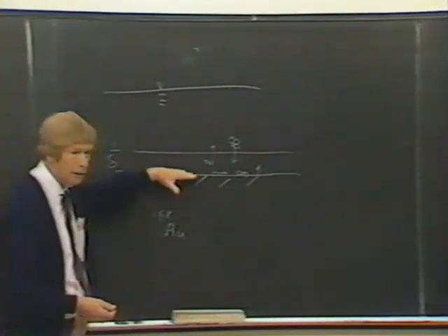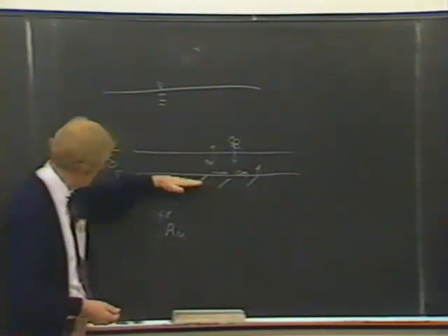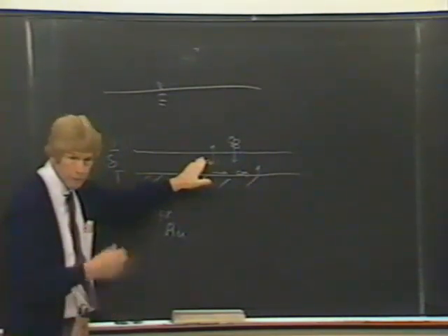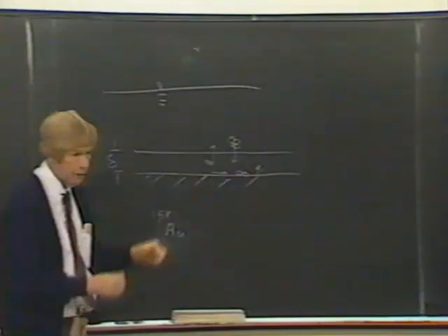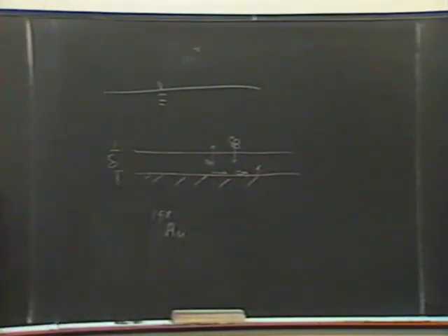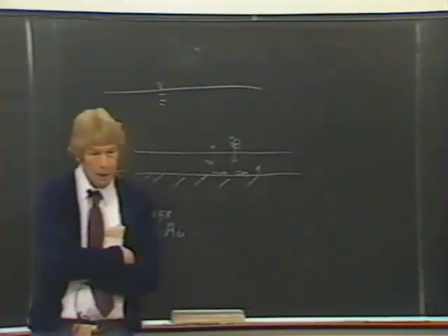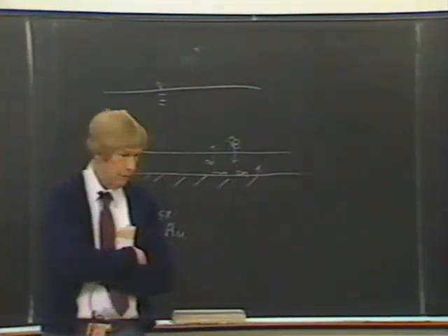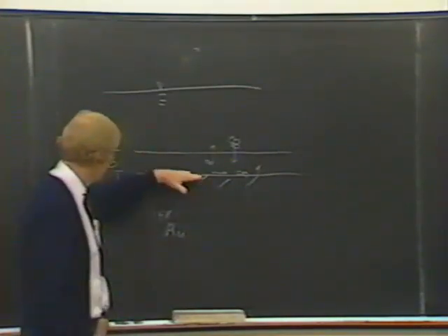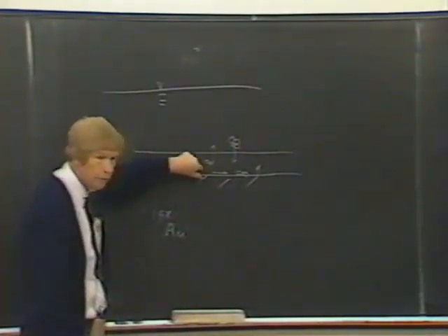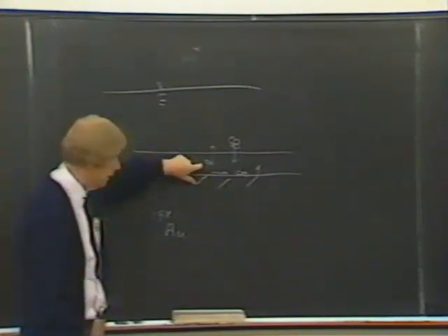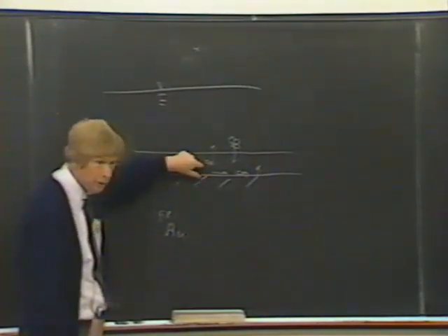These data really added fuel to the question about whether there's interchange with the bed or not. And now I think it's generally understood that there is interchange with the bed, and that this area is an area of breakup, or it could be an aggregation of particles if the velocity gradient is really low, and that when there is a breakup, the particles re-aggregate in the lower velocity gradients immediately above this region.